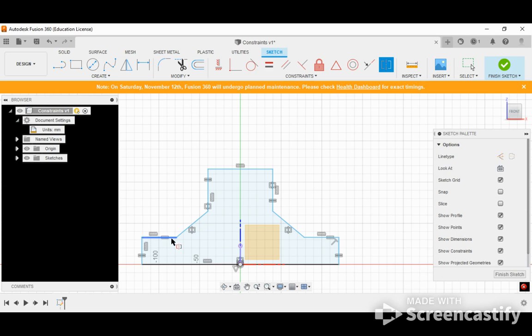It's saying it's over constrained because it means that I've kind of already said that. Somewhere in here that ended up working out well. That's fine. Yeah, I can see where it is. This length is symmetrical. Yeah. Okay, so now this is starting to look more like the right shape. Once you've used your constraints to make it the right shape, then you use your dimensions. So we're actually good for this here. This is the right shape we're looking for.